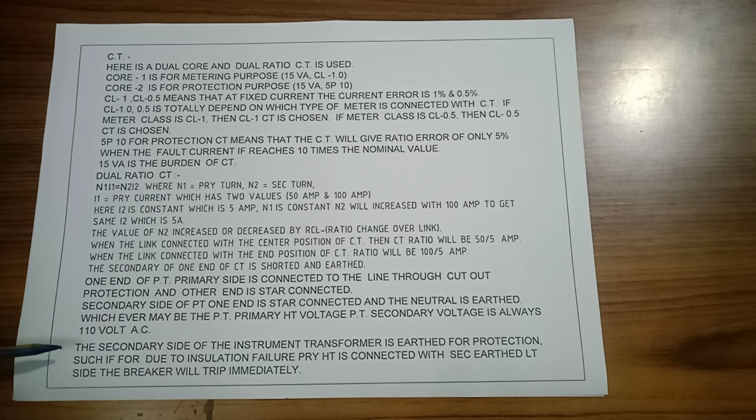The secondary side of the instrument transformer is earthed for protection. Such that, if due to insulation failure, primary HT is connected with the secondary earthed LT side, the breaker will trip immediately.